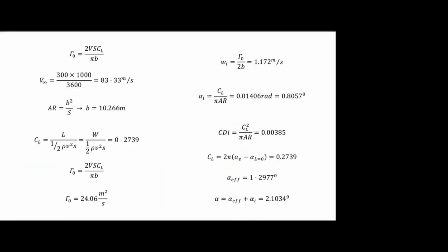See, whatever the alpha value you are getting from this equation, it will be in radian. Okay, don't put degree. Everything is a dimensionless number. CL is dimensionless, aspect ratio, b squared by S, also doesn't have dimension. So what you are getting is radian. You should not put this value as a degree. Okay, don't forget. Alpha i, whatever you are getting, is always radian, but you can convert it into degree if you want, or otherwise you can leave it in radian itself. But don't put degree for this value. It is radian. That's it.